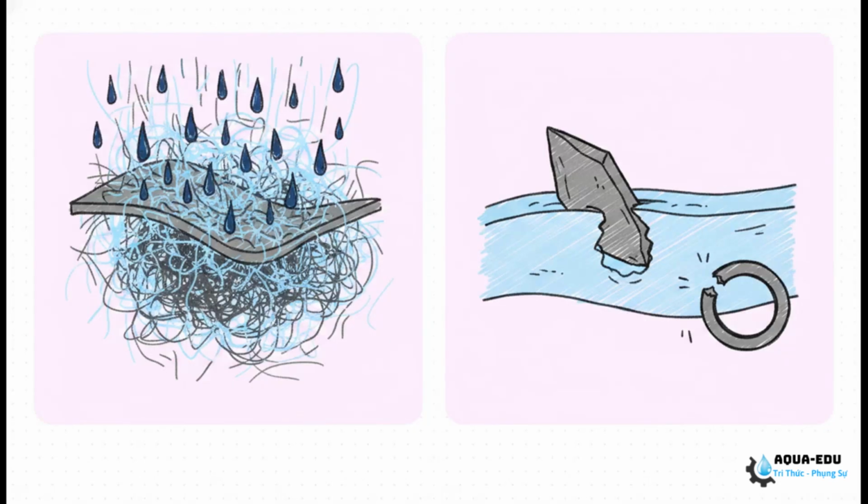We can really split these into 2 camps, chemical versus physical damage. Physical damage is usually localized. Maybe a sharp carbon particle scratched a membrane or a pressure shock tore an O-ring. But chemical deterioration? That is a plant-wide disaster. Free residual chlorine is particularly lethal.